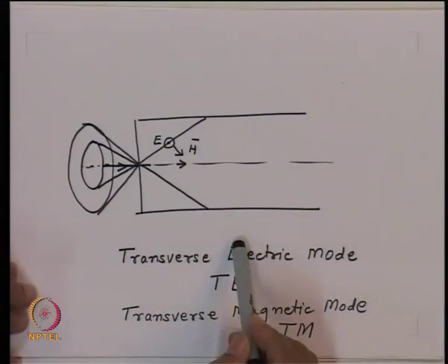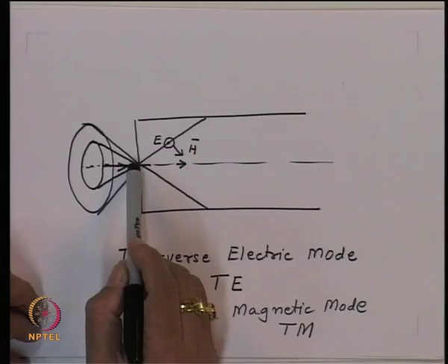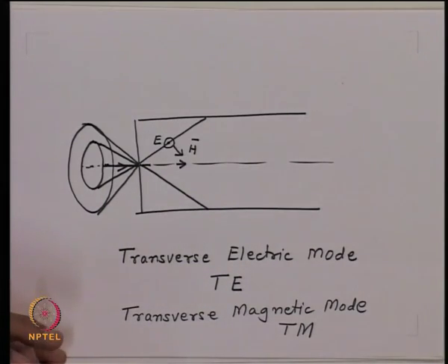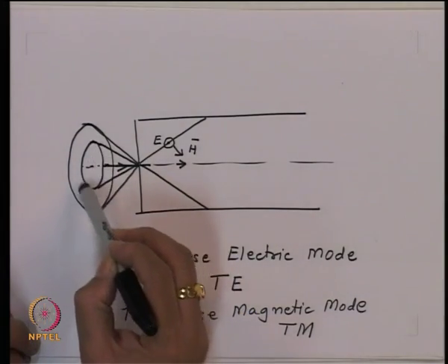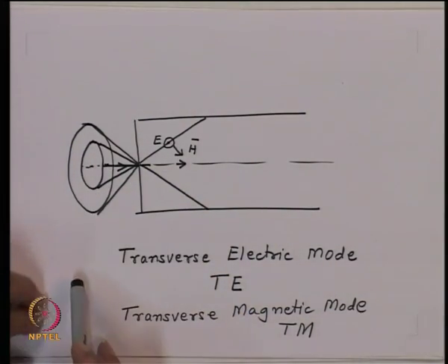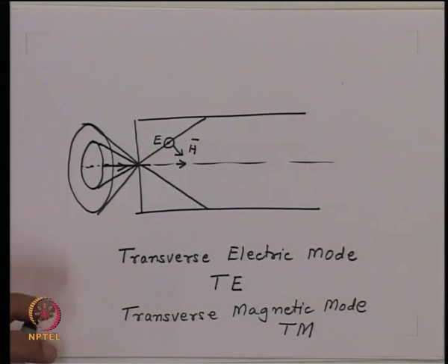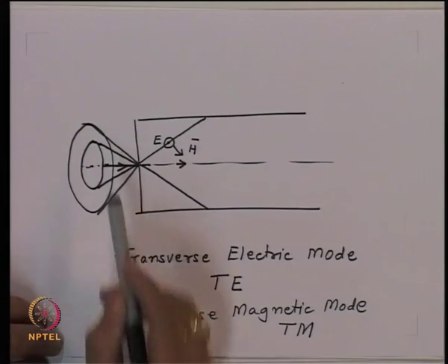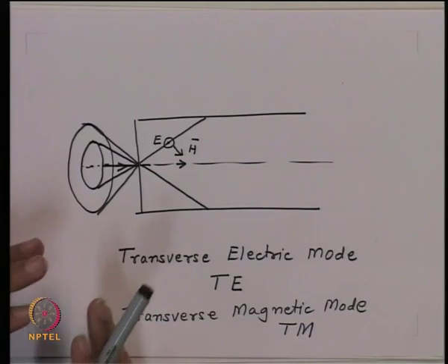So, now I have a situation where a large number of rays go and energy propagates on the optical fiber, or a second situation where only one ray goes along the axis and there is no dispersion on the optical fiber. Since we have seen that each ensemble of rays launched at a certain angle creates a definite intensity pattern which we call modes, when many angles are possible inside the optical fiber, we call that fiber the multi-mode fiber.